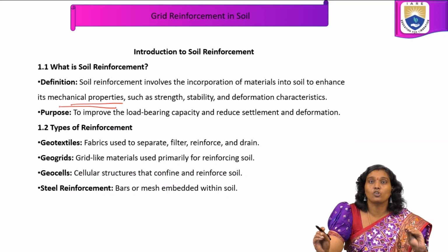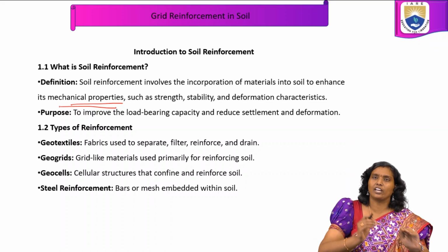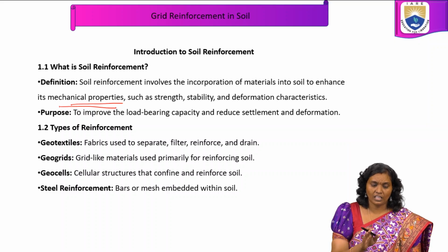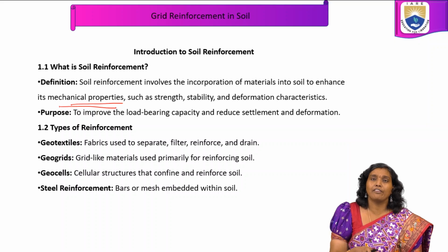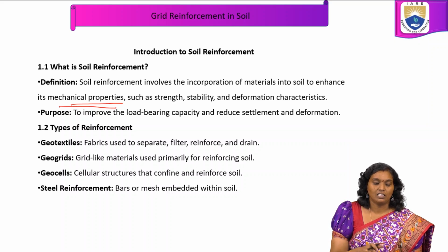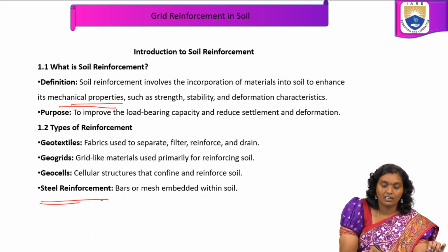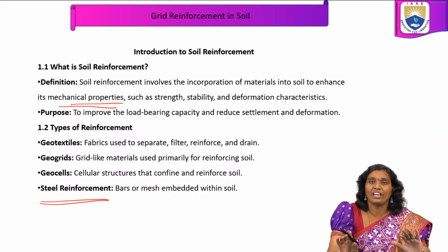This is for the purpose of improving the load bearing capacity and reducing the settlement and deformation. Different types of reinforcement are available: geotextiles, geogrids, geocells, and steel reinforcement.